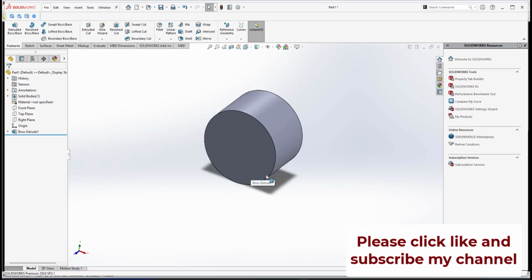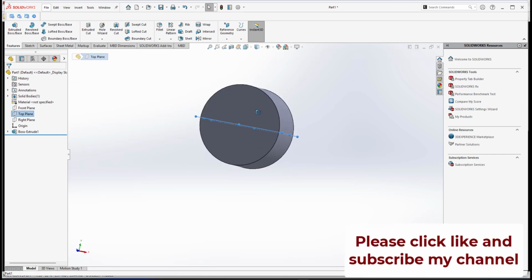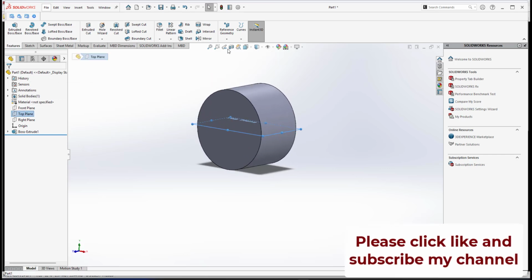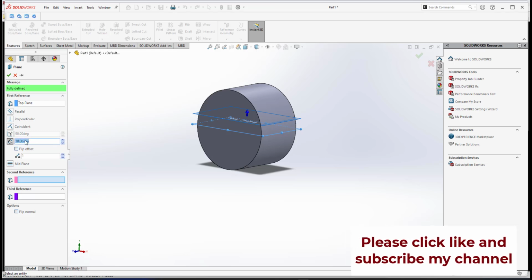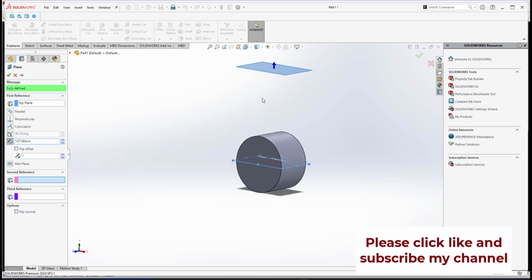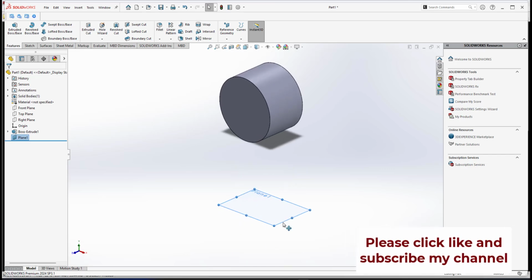Alright, so I will do a reference plane, since if you look, the top plane is really in the middle of that cylinder. So I will add another plane here. The distance is 127, so I will go for 127. But the side is not right. By default it goes to the top side, so I will go for flip and it goes to the bottom side. So this will be my plane for me to do the handle.